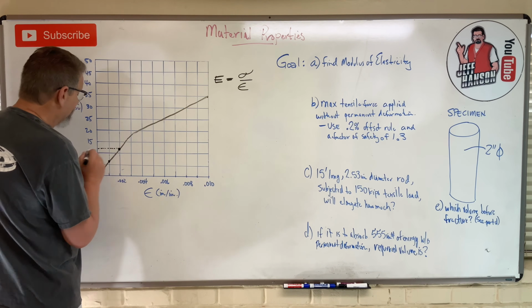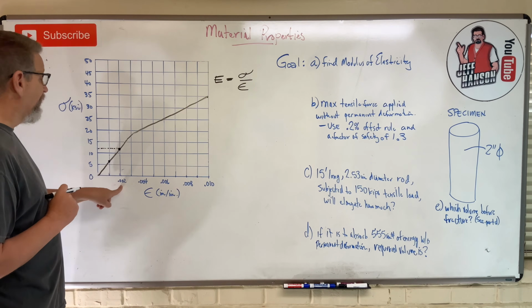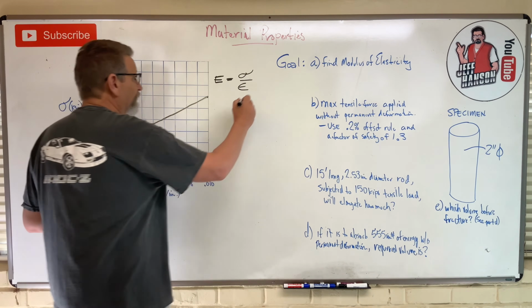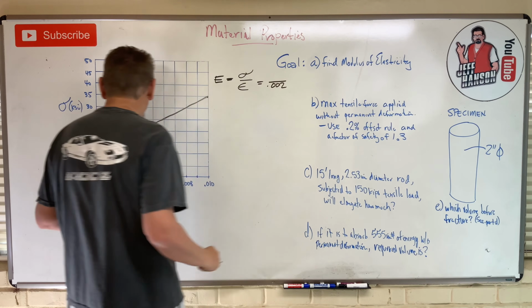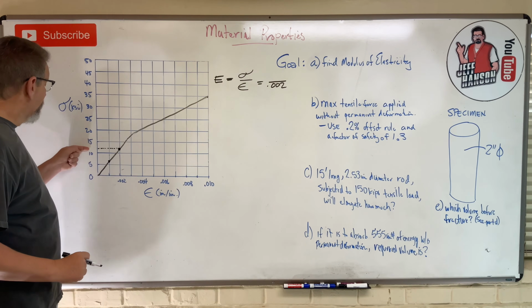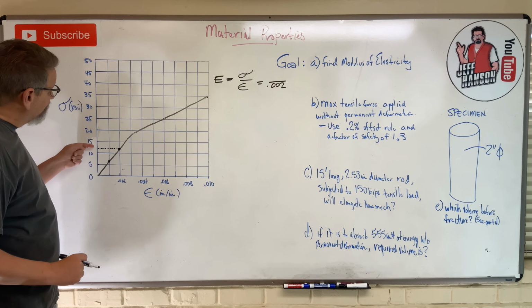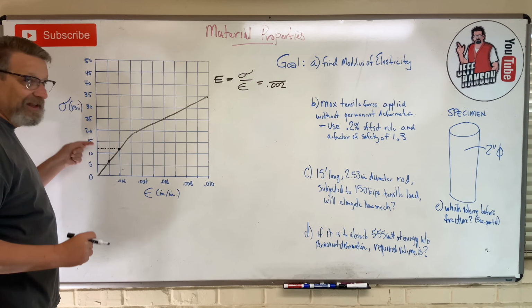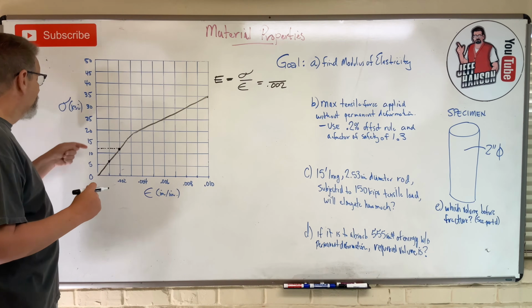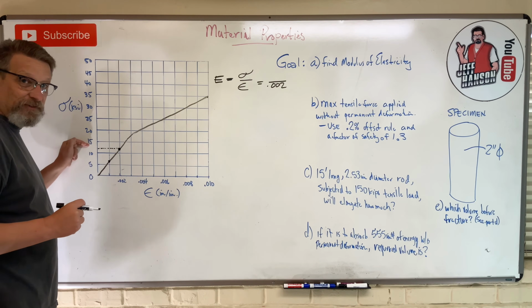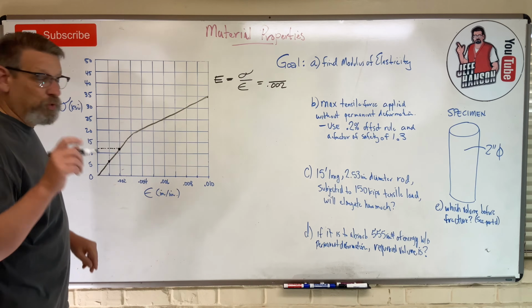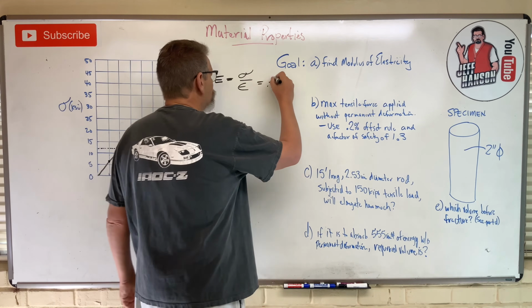And then where does that point intersect? Well, on the bottom it intersects at 0.002, so I know that one. And on the top, the question is what is that number right there? To me, it looks like it's just slightly less than halfway. So if halfway is 12.5 between 10 and 15, I'm going to call that 12. So 12 KSI.